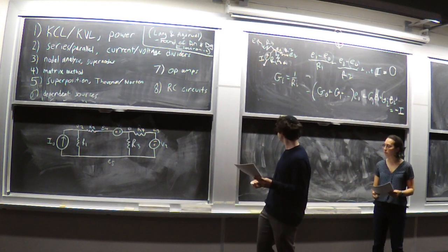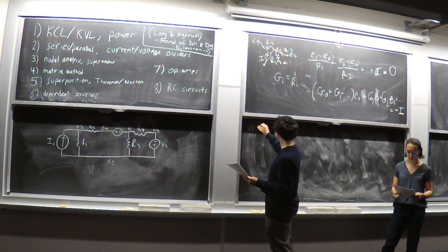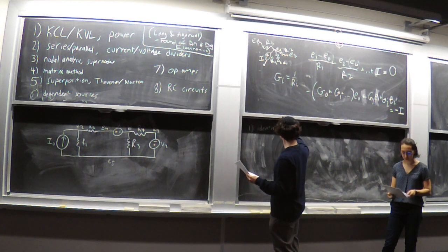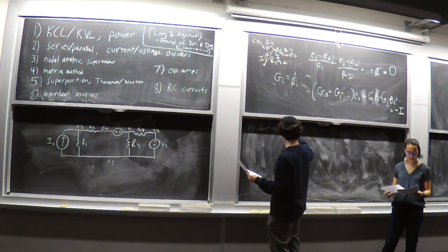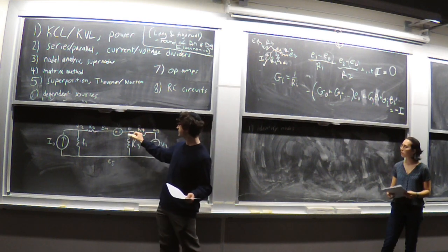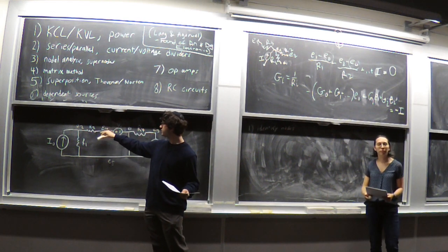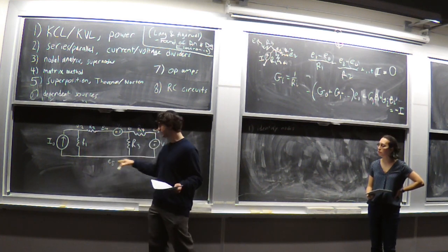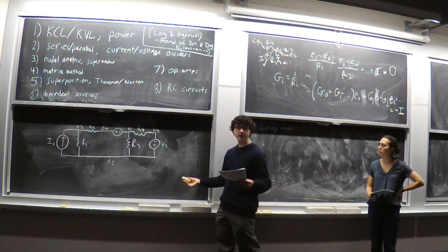So the first step of nodal analysis is to just identify the nodes. So I've done that in the circuit over there. Right, so we have 5 nodes here. It's basically any location of connected wires. So, you know, there's one giant node here at the bottom, I've labeled it E5.